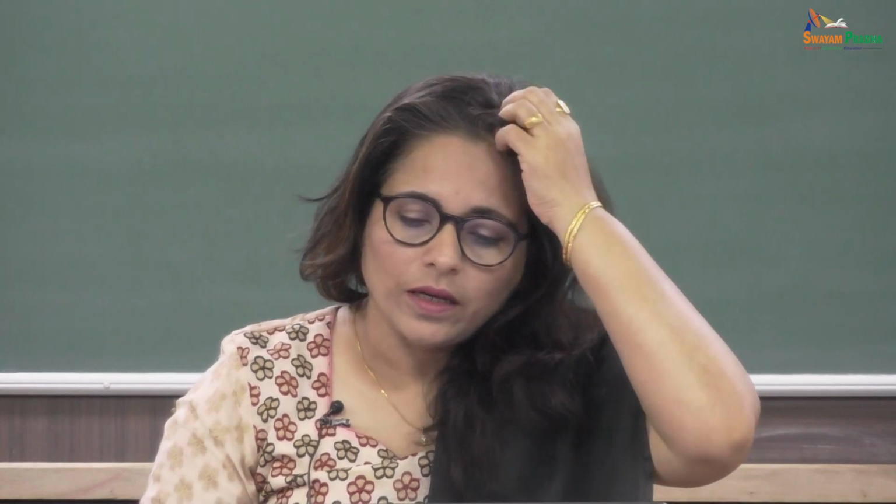Hi, so welcome back. We are into 3D turbulent boundary layer formulation. What we stopped at last time was that we developed some integral relationships, with the hope that we would get a little closer to the solution. Again, we are at a crossroads where we see that even a well-formulated 3D integral theory is hardly easy, and we still have to solve PDEs. So we're taking this up from there.